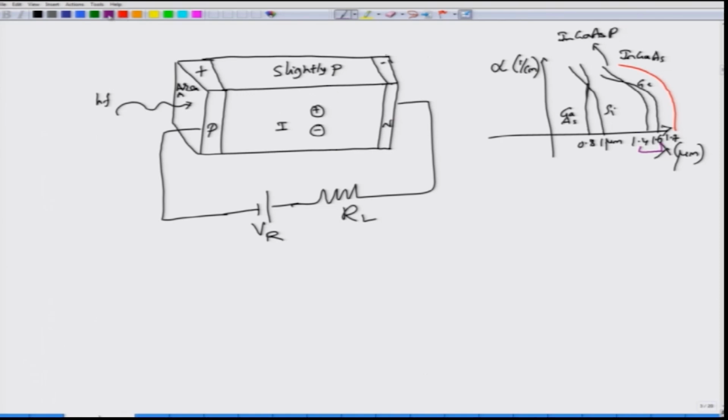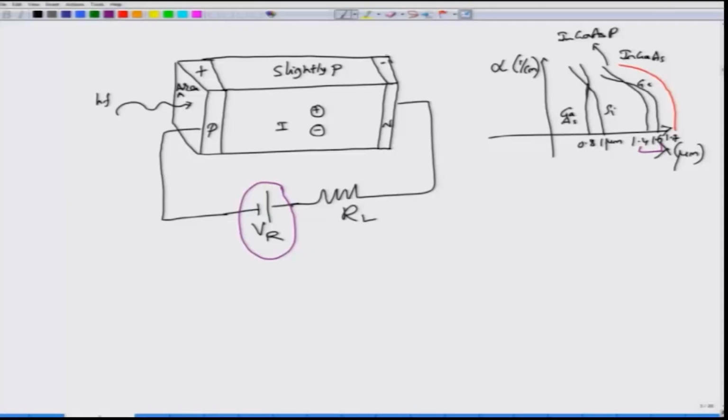Look at where the biasing is. If you look, the bias is in such a way that there is a depletion layer in the intrinsic region. The amount of depletion layer actually starts to increase as you increase the reverse bias voltage, correct. So, as the reverse bias voltage increases, the amount of depletion region also increases. What happens during depletion is that due to this negative polarity, the holes which are present here, which are carrying positive charges, would be attracted, and this hole actually gets attracted and then flows through the battery terminal.